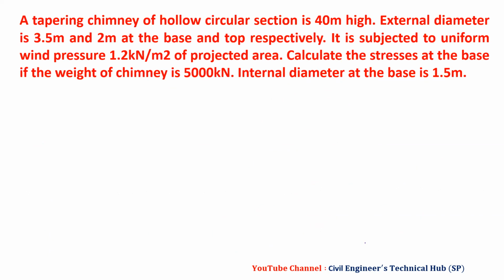Now we will switch over to the last problem of this, a tapering chimney. Tapering means we have different diameters. We are given 3.5 at bottom and 2 at top, so it is like this. In such a problem, you have change only in the projected area, remaining things are same. So we have to consider the projected area. This is 2 meter, this is 3.5 meter. Now we will go first with P, which is given as 5000 kilonewton.